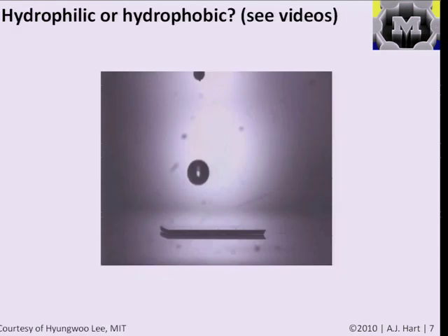And one of the real practical challenges has been that it's been hard to design surfaces that are non-wetting to liquids with low surface energy, because liquids with low surface energy will be much happier to spread out and cover a surface, since that will possibly decrease the overall free energy of the system. That has practical implications for things like cleaning up oil spills, because oils and solvents have low surface energy, and it is also important for separation of liquids with different surface energies.